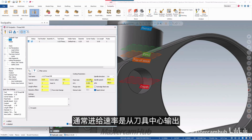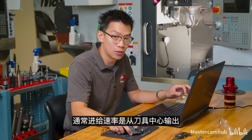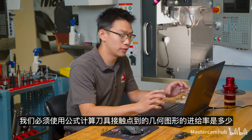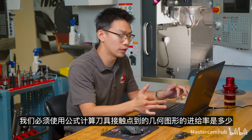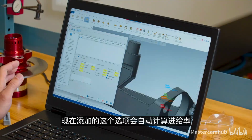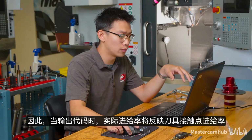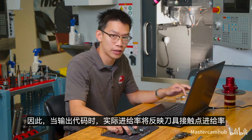So normally the feed rate would be output from the center of the tool, and you'd have to use a formula to calculate what the feed rate is where the contact point of the tool is to your geometry. Now, we added this checkbox to automatically do this for you, so when you output your code, your actual feed rate would be reflecting your contact point feed rate.